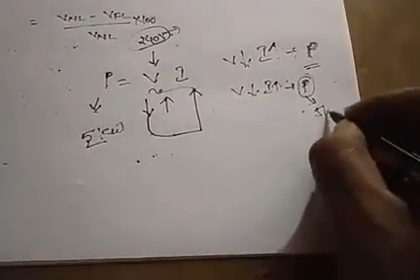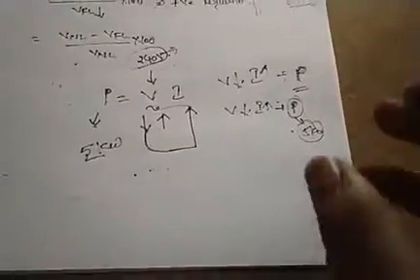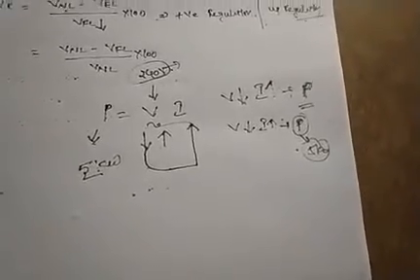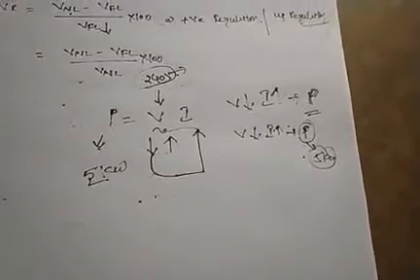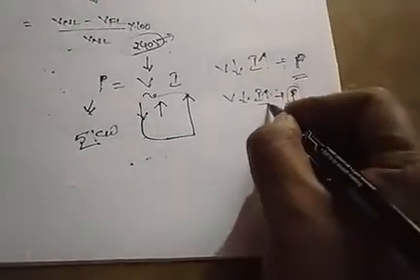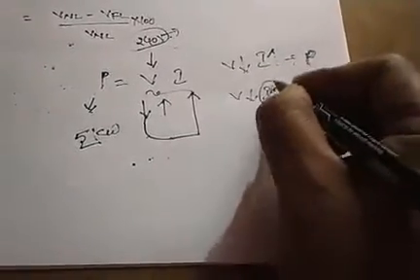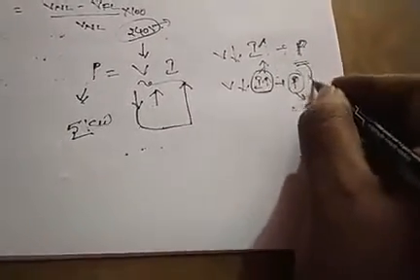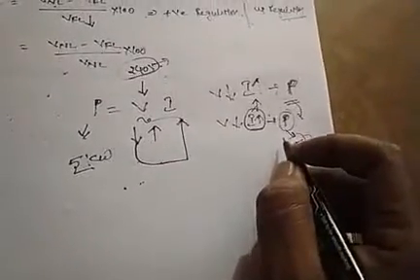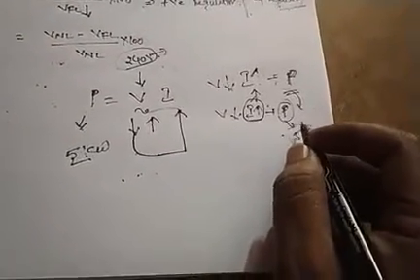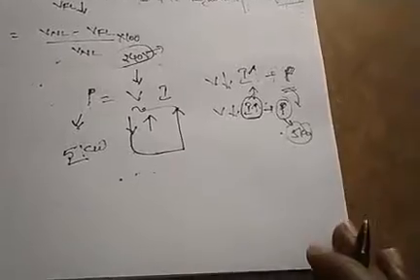My 5 kilowatts, so my power is going to be constant. You designed that machine with this power, right? So if the voltage reduces, my current increases. You know what about this? If the current increases, my windings get damaged, right? There will be overheating in the machine. My machine will definitely be destroyed, right?